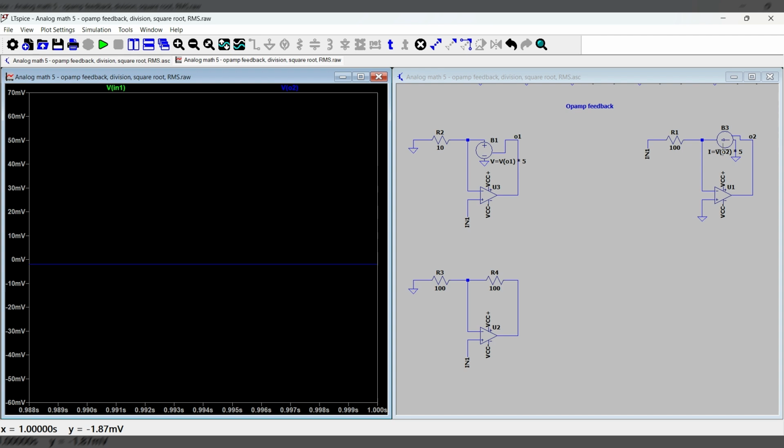Because the transistor has a voltage to current relationship, basically e to the power of some VBE equals the collector current, we can use an inverting config to invert that to become a log amp. Whereas here, today, I'm only using voltage to voltage transformations for my circuits.